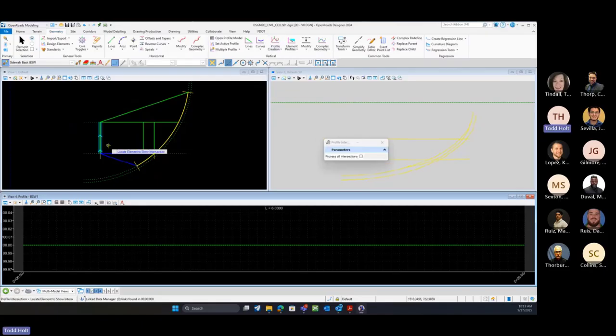So we know on this line, we want it to tie into our sidewalks. And then from our sidewalk, we're going to transition down to that. So we're going to build those profiles in there. And then for the ramp down to this, we're going to project that to our 12-to-4. But on this one, we're going to build our profile first. We're going to tie that into our existing slopes of our sidewalk. I want to do our profile creation, profile intersection point.